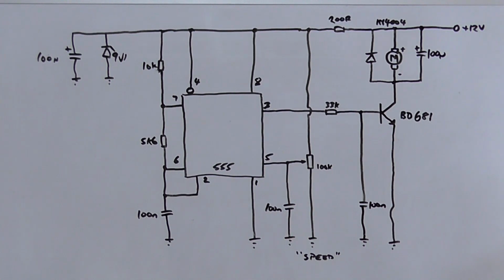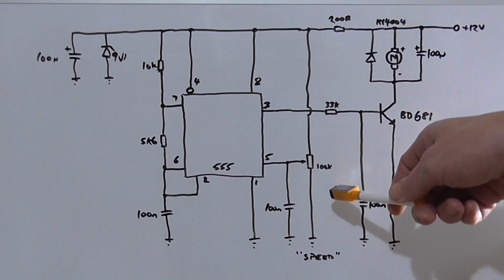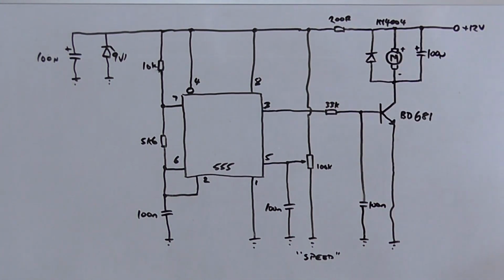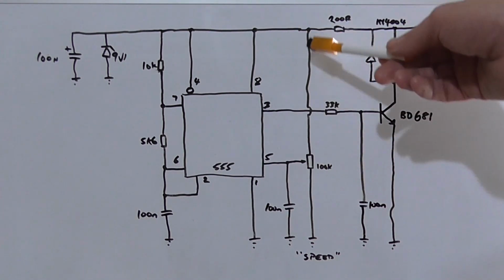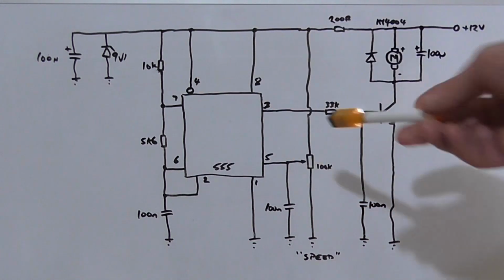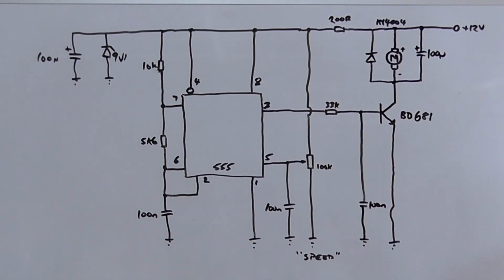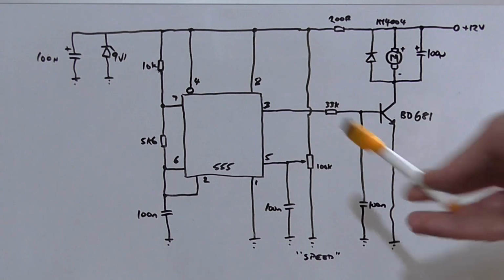And we go from a duty cycle of roughly about 3%, and when the pot is rotated closer to maximum, the duty cycle will increase to roughly 99%, and when it reaches maximum, when the control voltage is the same as the supply voltage, the duty cycle then becomes nothing, or 100%, and the output is constantly high.